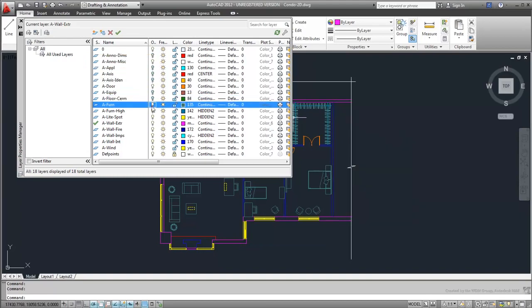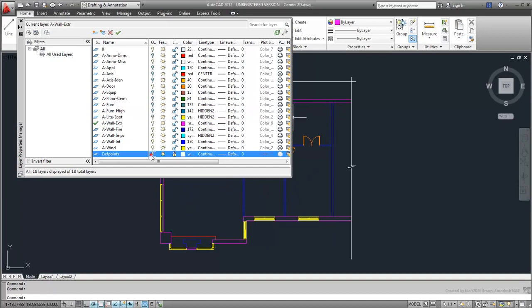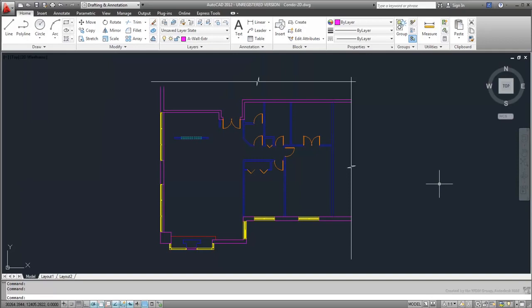Layer management is the first step in preparing your CAD drawing for export to 3ds Max. The next step involves your level of expertise in AutoCAD. Power users may opt to build their 3D components in AutoCAD directly, and then export these 3D entities to 3ds Max for material, rendering, and animation work. For the average AutoCAD user, though, the person who spends every waking moment working on 2D tech drawings, then it's often easier to do all 3D work in 3ds Max, as it excels in that area.